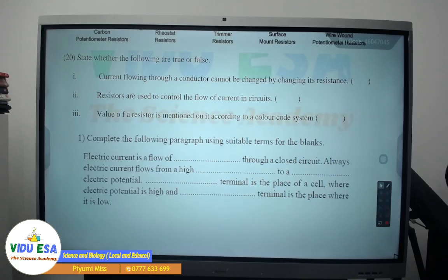Milliammeter or microammeter can be used to measure small electric currents. An ammeter or milliammeter has positive and negative terminals. The positive terminal is red and the negative terminal is black. When connecting the ammeter or milliammeter to a circuit, those terminals should be connected properly. To measure a current, an ammeter or milliammeter is connected in series to the circuit.